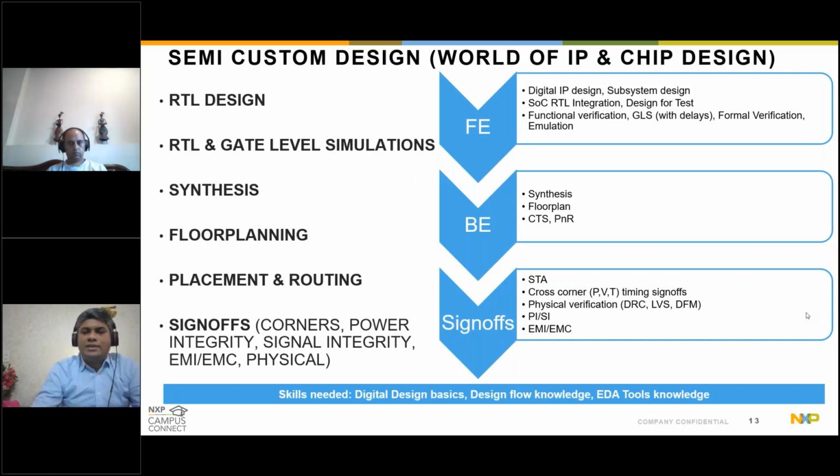Okay. Once this blueprint, which is called the floor plan, is done, then you go into what we call placement and routing, which is the physical aspect of translating those layouts where the full custom guys had made certain layouts. You remember, those layouts now get printed on these tiles, basically those rows, and we'll cover more about it in the chapter section. But the place and route basically happens here. Clock tree synthesis also becomes extremely important, where you ensure that the clock, which is the heart of the chip, is traversing across the entire design in the right way, the way it should.